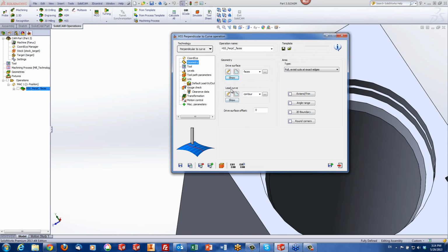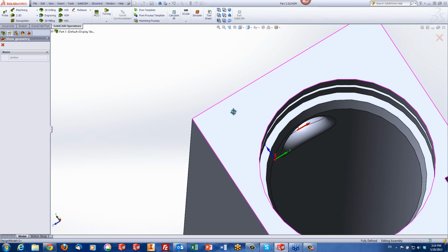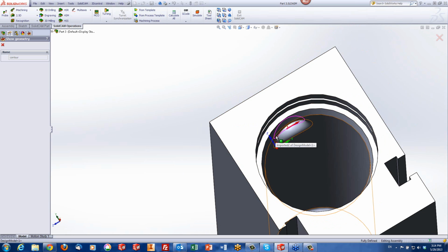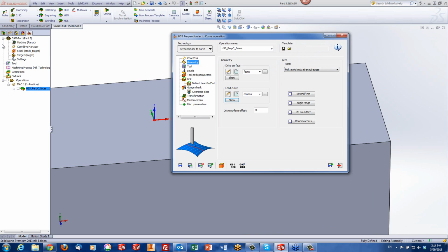The lead curve itself was this curve over here. Now, the way the tool is going to work, because I told it to work perpendicular to this curve, it's actually going to work back and forth, up and down on this surface. So the pressure on the tool actually ended up being up and down on the tool instead of to the side. Obviously we had to work pretty slow, but this was able to be done, and it worked without any problem. Now, there are other things we also had to look out for over here. Let's go through the operation and we'll see exactly what was done.